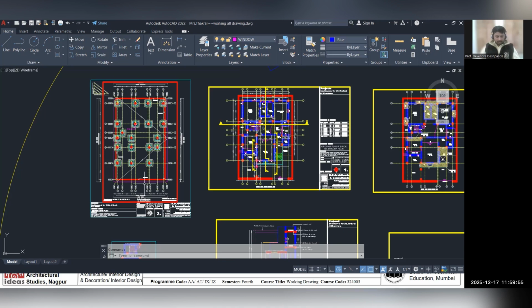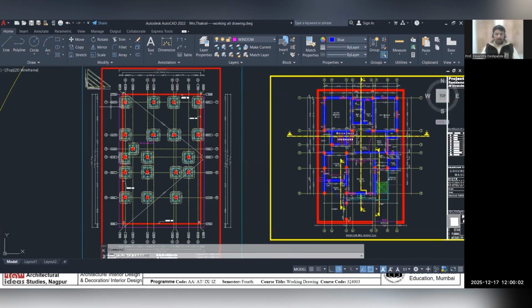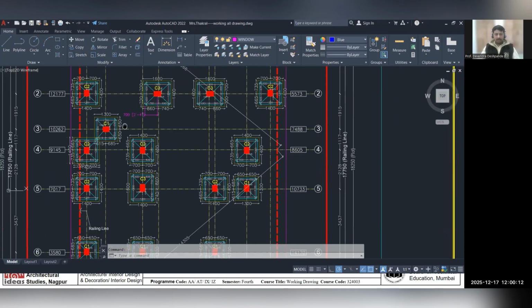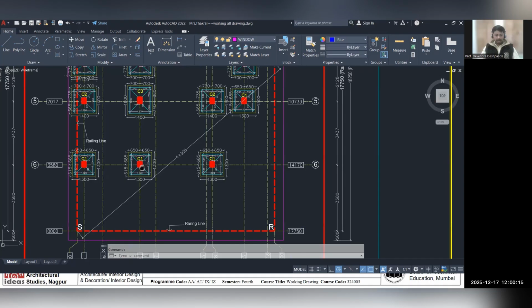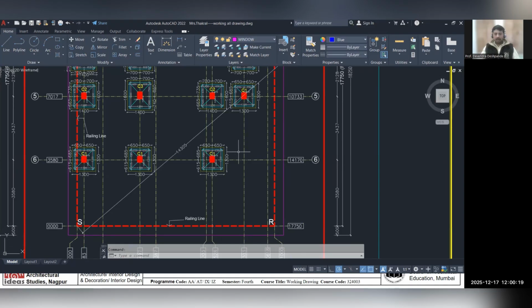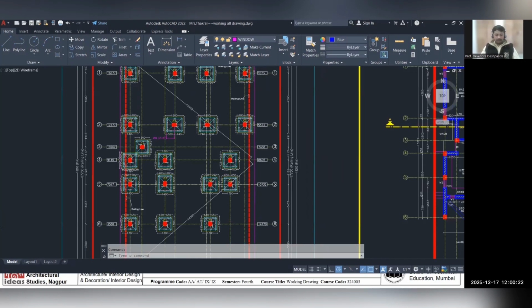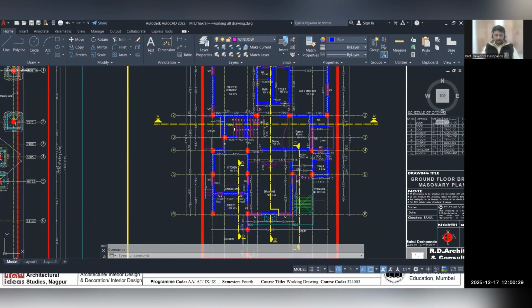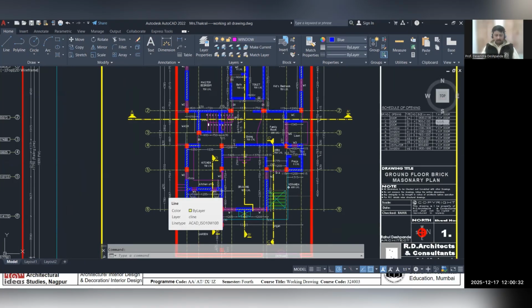This was the very first TLO of this unit. TLO 2.1, draw building envelope using diagonals and coordinate method, talks about the location of your vertical structural elements as columns, the location of foundation with respect to the plot boundary, what are the side margins left and space left in order to manage machinery and raw material on site. We will discuss this drawing later on. Prior to that, we'll take care of the third TLO first. That is 2.3, floor plan drawings with important building elements like walls, columns, doors, windows, projections, weathering protections, and cladding.